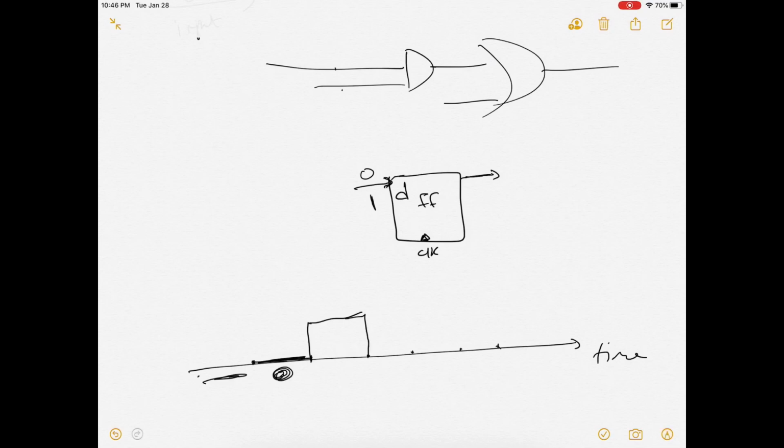If the input stays 1, we will also see an output of 1. If the input changes to 0, we will see an output of 0 at this clock rate. Every period of the clock, whatever is on the input will become the output. So this is a basic flip-flop. It takes the input and puts it in the output at every clock rate.